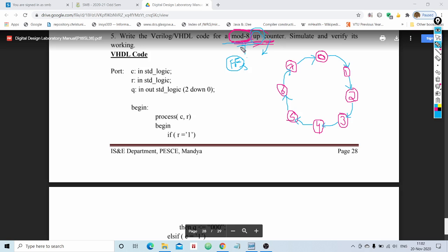But one more piece of information which is very important is how many flip-flops you need. That is an important point that you need to address before jumping into the actual design of the counter. Clear? It is very simple to find out the number of flip-flops required for designing the counter. Just look at the maximum state that a counter can reach.